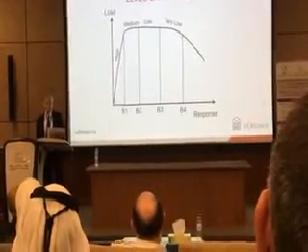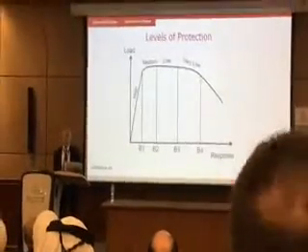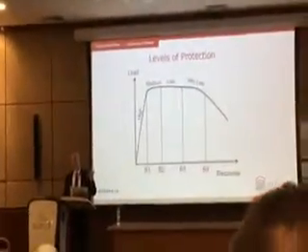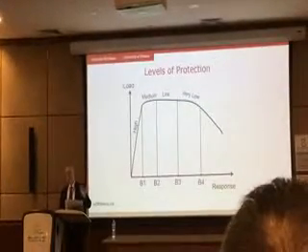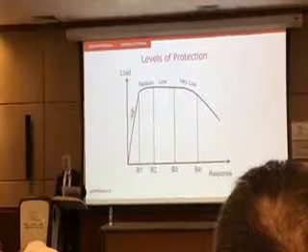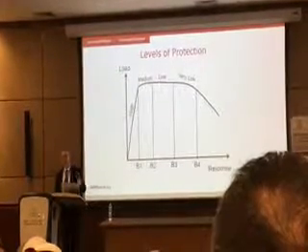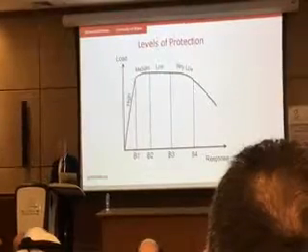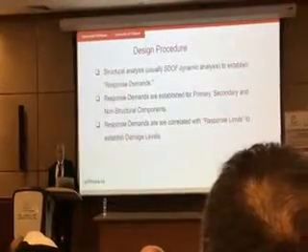It's on the verge of collapsing, but you allow the building to displace this much. So once again, given level of protection that the owner is willing to pay, then as a structural engineer, you design it such that displacement, nonlinear displacements are attained within that category.